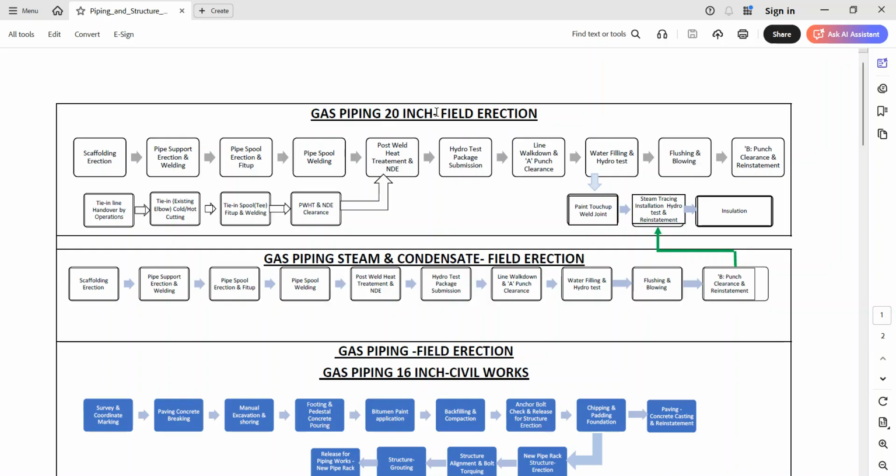Then you proceed with the post weld heat treatment, as the pipe thickness is more. It is a heat treatment process where they use fire blankets placed over both the pipes, and for heating arrangements you also have some kind of heating devices. For this it also takes some duration. You cannot do it one joint by one joint, so you need to have 5 to 6 joints, so that the PWHT team also gets a sufficient work front. Then you start with the post weld heat treatment.